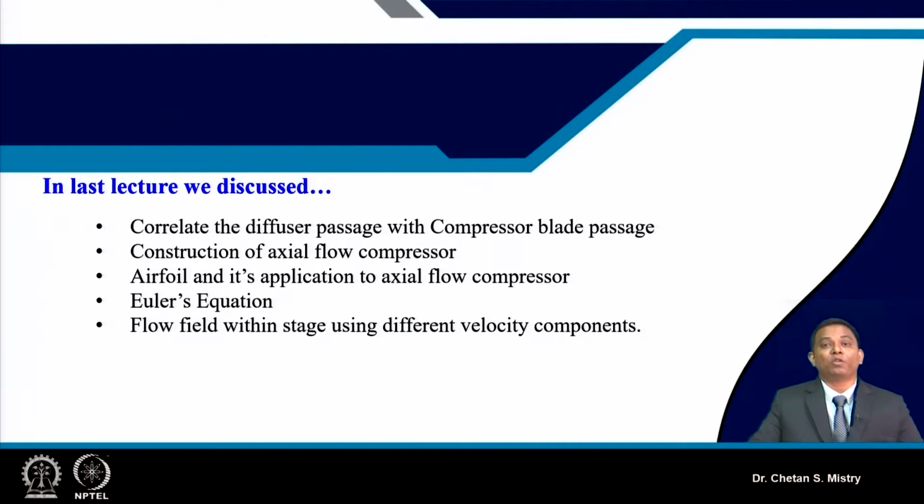Many times people bend a plate and consider that as a blade. Yes, that can also be used as a blade for making a fan, but just realize that the pressure rise we expect is large, and for a curved blade that pressure rise will not be achieved as per our expectation.